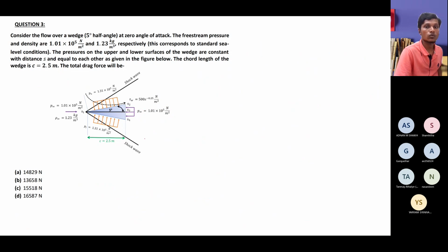So let's go to the other component, in the same way how we did for the upper surface. Let's see the pressure distribution in the lower surface. As we already told you, the pressure distribution in the upper and lower surface is the same. The value you will get is the same as what you already got for the upper surface. But let's see with our sign convention, that is PL sin theta DSL equals the integral.